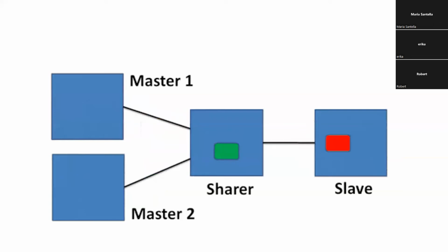So what our TSH module does is, if two commands come in simultaneously, it will send one command through, allow the slave device to respond, and forward the response to the appropriate master. Then it sends the second command through once the first command is either completed or timed out. So for this example, let me go to the next slide.